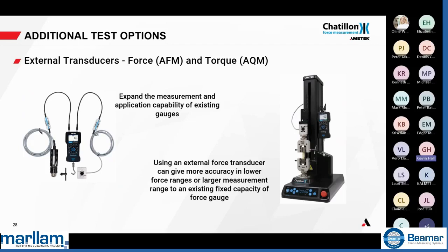It's going to pass that data back out to the force gauge in the form of inches or millimeters, so metric and imperial. And you can actually take readings from the gauge, and you can use stop conditions of extension to control the gauge and control the movement of the test stand. So not only can we move to a certain force, we can move to an extension.